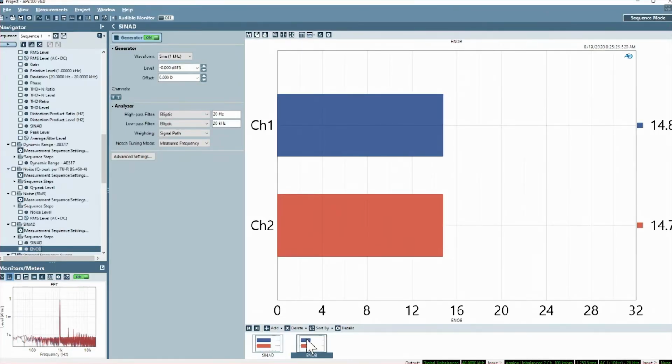Again, there's a little bit more detail to it, but the basic thing is we can take the SINAD or the THD plus N and divide it by 6.02 dB, and that tells us how many useful bits we're actually getting. So in this case, you can see that in this converter, we're actually pretty close to its theoretical 16-bit performance. We're getting 14.7, 14.8 effective bits.